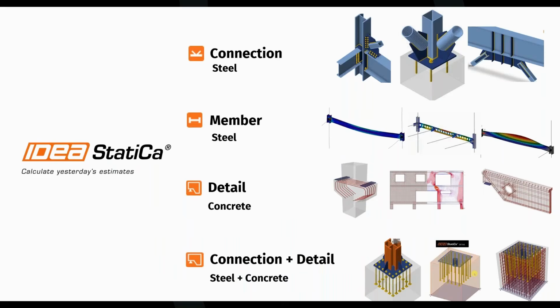Detail is focused on the local zones of a concrete structure. We're talking about areas like corbels, frame corners, deep beams, or regions around large openings, places where stress flow becomes nonlinear and simple hand calculations or spreadsheet checks just don't give us the full picture.